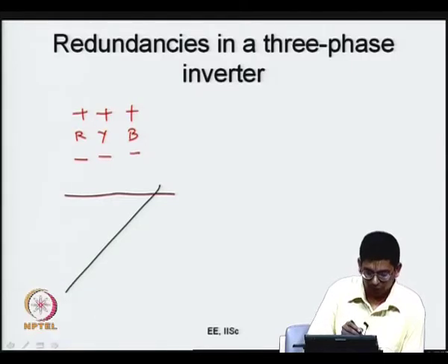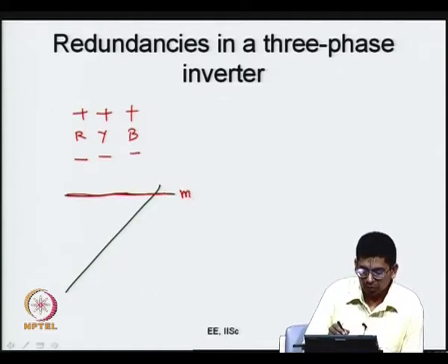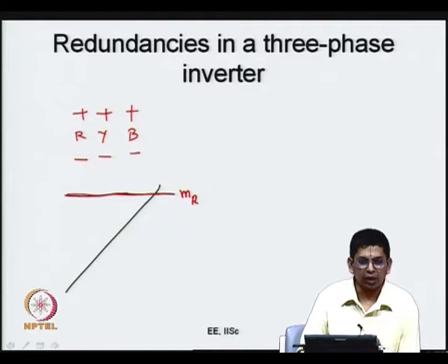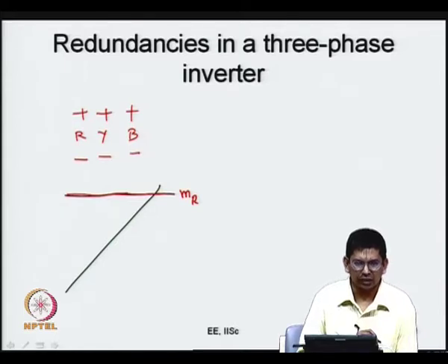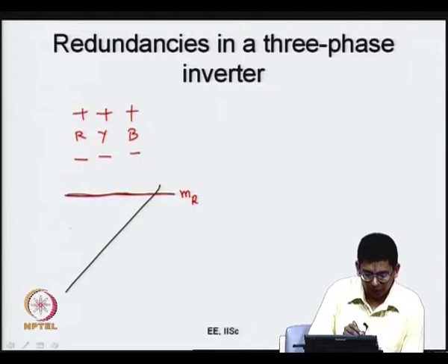Yeah, I think that is a different version of red. So, alright, this would be proper. This is what I would call M, or the modulating signal corresponding to R phase in this carrier cycle. As I said, the carrier cycle is much shorter than the modulating signal cycle, therefore the modulating signal is a flat line here. Then let me go and indicate the Y phase signal.